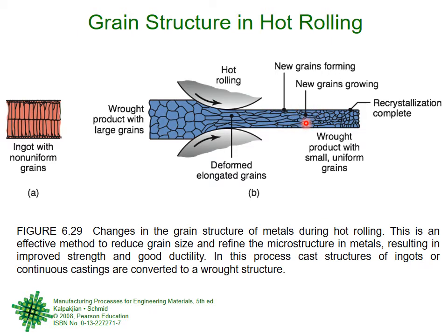So you remember the annealing process and so on. When they are heated and cooled, then nucleation of new grains and recrystallization happens. But these recrystallized grains are still smaller in average diameter than the original ones. So the strength will be higher, right?